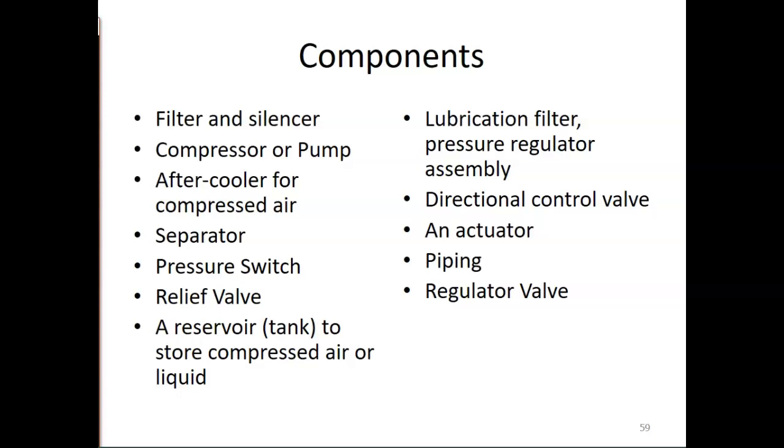Regulator assemblies are what you'll be seeing in there. They're basically the pressure gauge, and they actually have a moisture filter on them as well. We'll talk about that when we get there. Directional control valves, or the short initials typically used, DCV. DCVs, because directional control valve is a mouthful, do exactly what they say. They control the direction of your fluid, whether it's a hydraulic or pneumatic fluid. It's directing it to where it needs to go so it can do the job it needs to do.